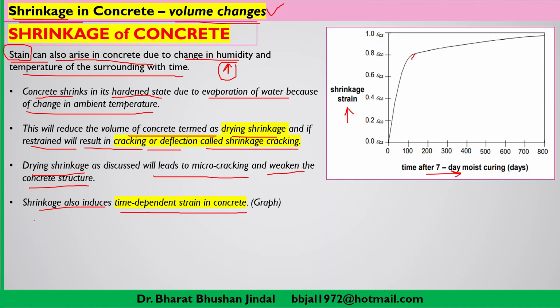So here we have written that shrinkage also induces time-dependent strain. That means the strain due to shrinkage also depends on time, which we can see here, and after a particular duration you may find that the curve is getting almost flattened.